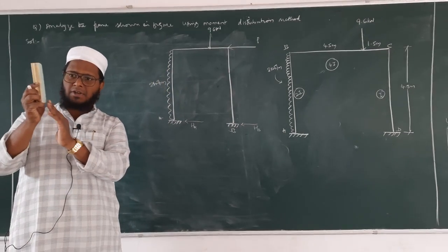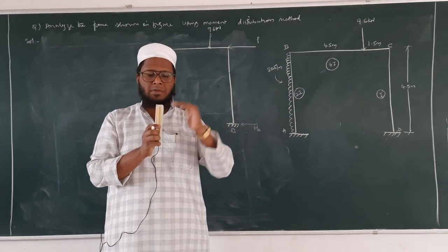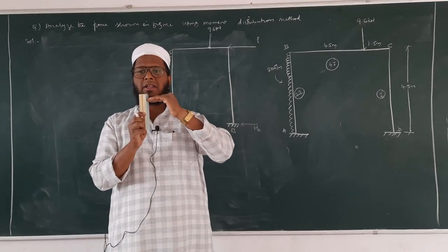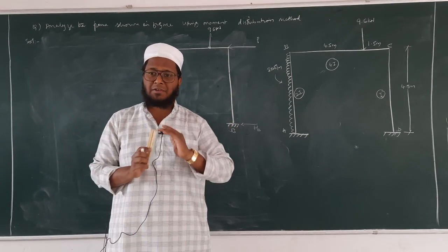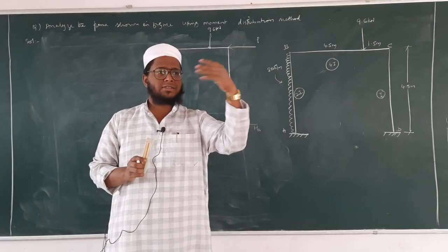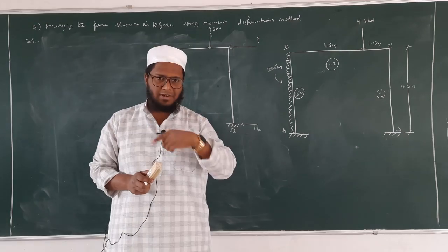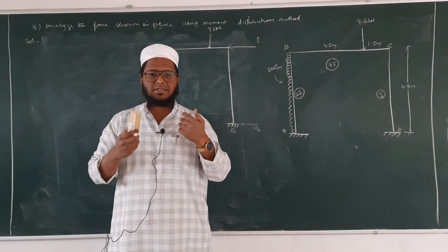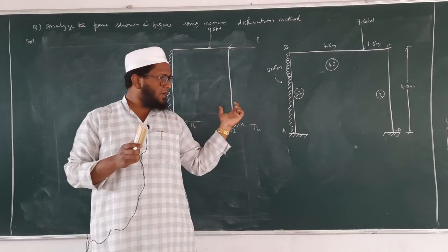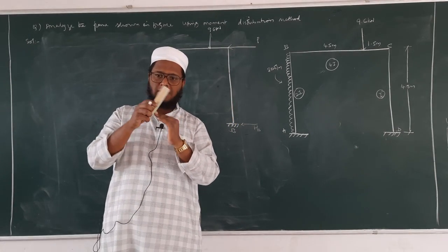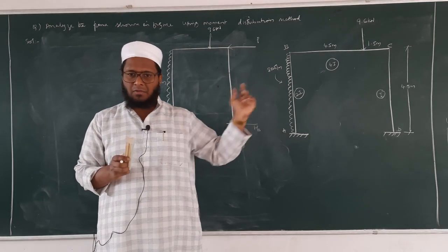The building is trying to get deflected in the left side. Okay. So I am assuming that I will apply one force here so that my building will be in its original position. That is in equilibrium. Our entire buildings are in equilibrium, isn't it? It is not moving. Sigma x is equal to 0, sigma y is equal to 0, sigma m is also equal to 0 there, right? In this entire building, sigma x, sigma y and sigma m is equal to 0. So that is why in this frame also, since it is trying to get deflected in this direction, I am applying one more force. Okay, that is P. Now we will calculate what is P.